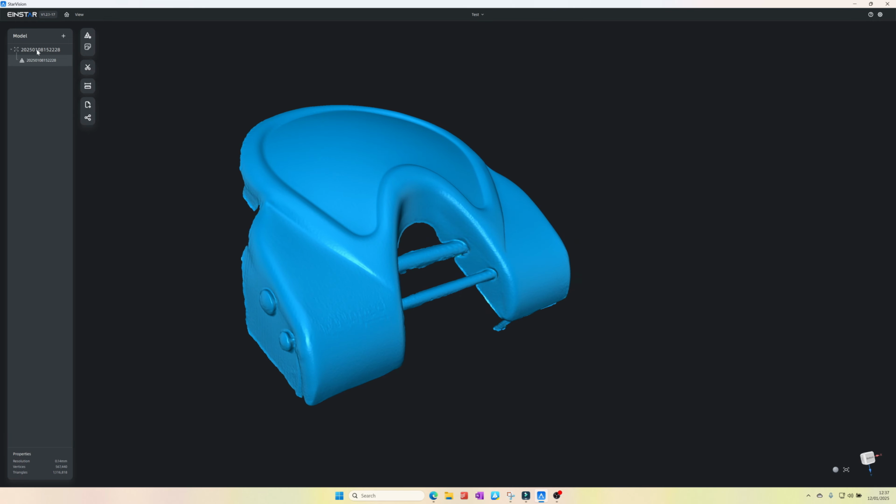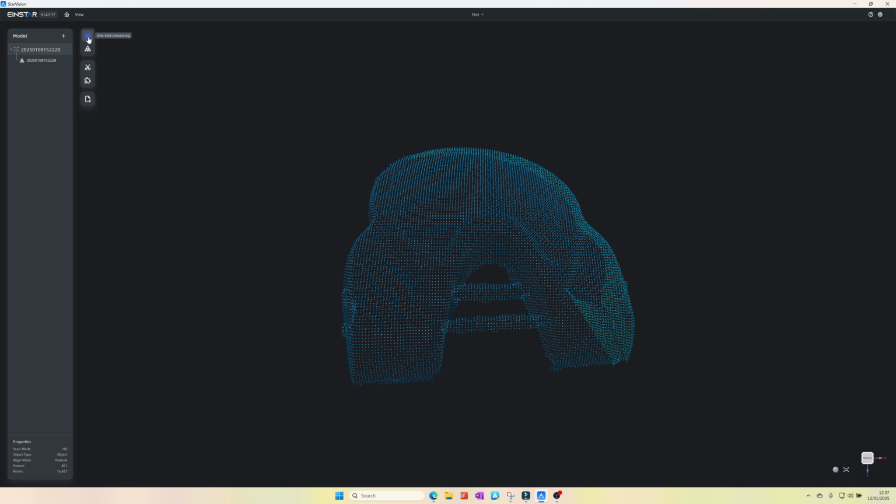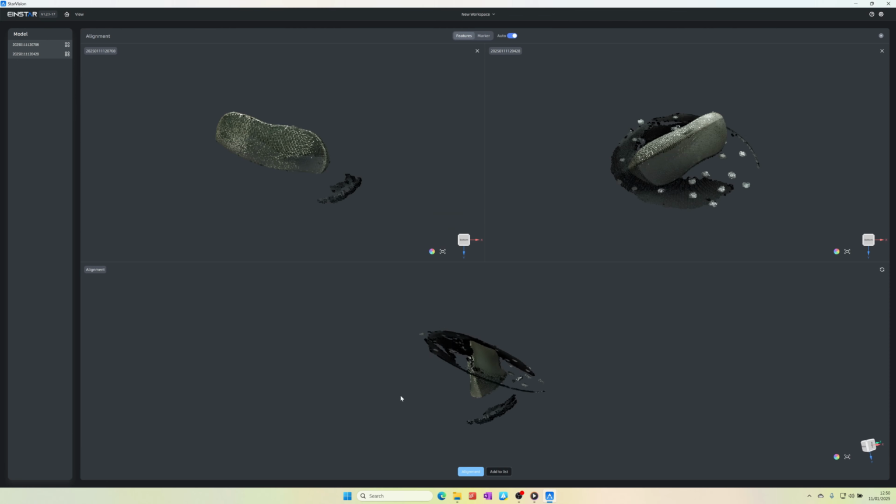This software allows for one-click processing, commonly called wizard, and manual mesh generation, replicating what happens on the scanner. There's the cropping tool called clipping on the scanner, which is a nomenclature inconsistency as they perform the same function. The alignment command is only available for the point cloud. As the name suggests, it aligns different scans of the same object taken at different times or orientations.